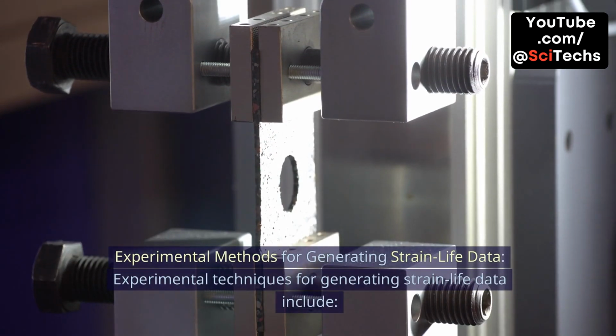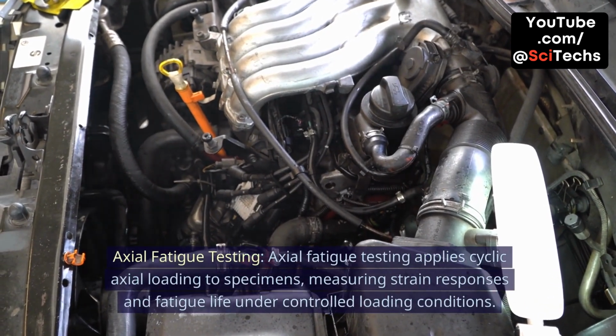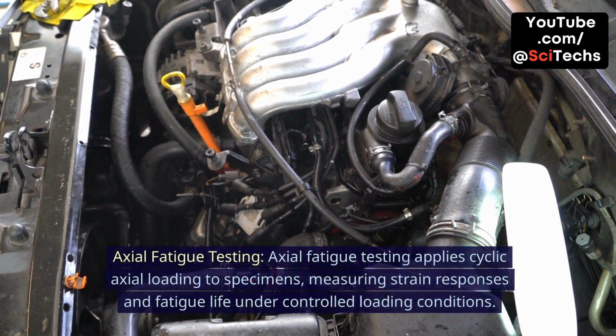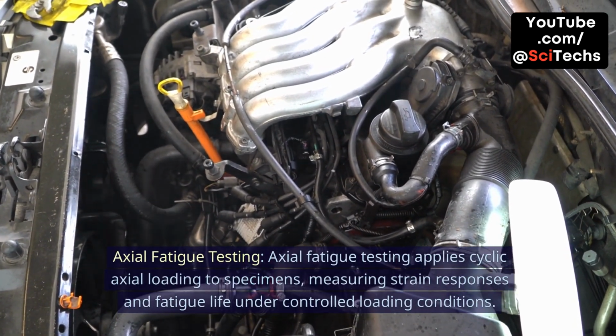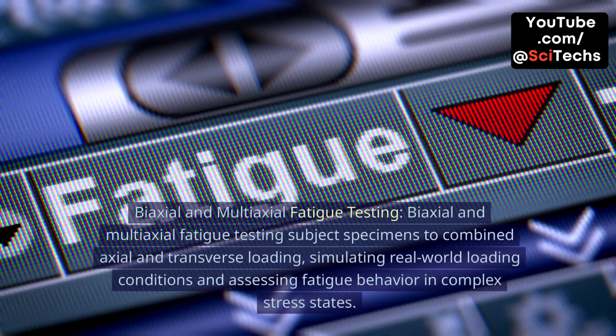Experimental methods for generating strain life data. Experimental techniques for generating strain life data include axial fatigue testing. Axial fatigue testing applies cyclic axial loading to specimens, measuring strain responses and fatigue life under controlled loading conditions. Biaxial and multi-axial fatigue testing. Biaxial and multi-axial fatigue testing subject specimens to combined axial and transverse loading, simulating real-world loading conditions and assessing fatigue behavior in complex stress states.